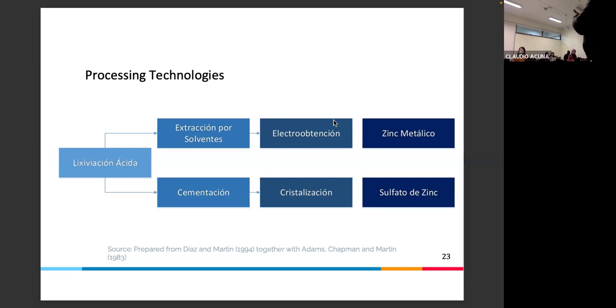From solid to leaching, as a process, it can be atmospheric leaching, or it could be autoclave leaching in case the kinetics are too slow. We need to go to a very high temperature, 200, 300. But in any case, from solid we go to liquid. And then in this liquid we have a soup, plenty of different ions. Depending on the concentration of the ions, if the concentration is low, we don't even think, you go through an ion exchange. If the concentration is in the range of grams per liter, we can think of solvent extraction.